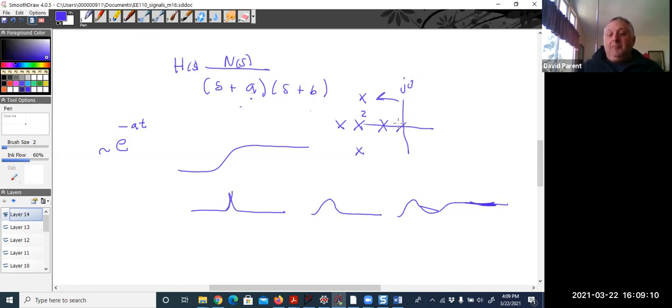But when we start getting poles at 0 and in the right half plane, we can get oscillators, things that integrate, and things that exponentially increase. And those systems are out of control. Sometimes you have some kind of robotic system where you put in a step impulse and it falls over. You don't want it to do that. And so you use control theory to make that not happen. And that would be the 5th topic.